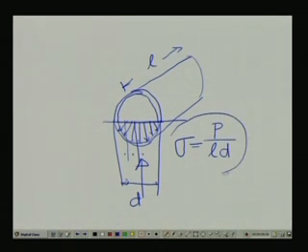So, this becomes a bearing stress in the case of the circular hole. Remember, whenever there is a circular hole and we have a contact with the shaft just described, we always take the area as the length times the projection.